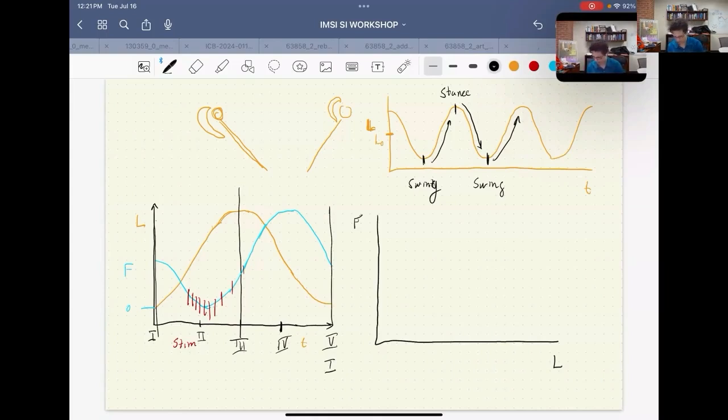So now I want to plot this on a work loop. Well, I've started off where the length is the shortest here at 0.1. But the force is not 0. So I'm going to make a 0 mark here, and here's the L min, and here's the L max, and here's my rough middle point. Well, since we did it around the center point, it would be like here.